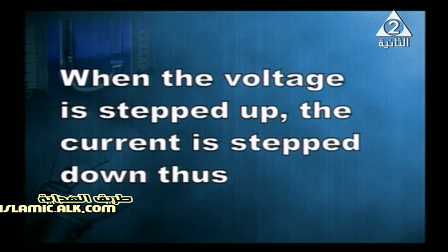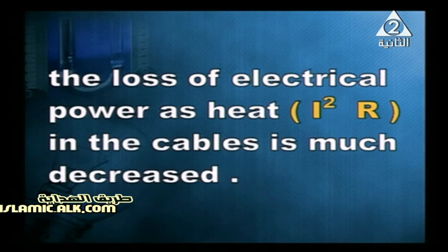When the voltage is stepped up, what happens to the current? The current is stepped down. Thus, the loss of electric power as heat, which is given by the expression I squared R, is much reduced, much decreased, since we decrease the current.